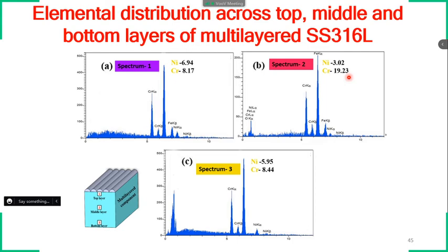That is why the elemental composition should be homogeneously distributed. If there is this kind of complication, we have to do heat treatment to homogenize all the elemental components throughout the component, which is unwanted work. So through fabrication itself, we should try to minimize all the microstructural heterogeneities and homogenize the elemental distribution. Due to this, a lot of research is going on into how to homogenize the precipitates and the grain size.